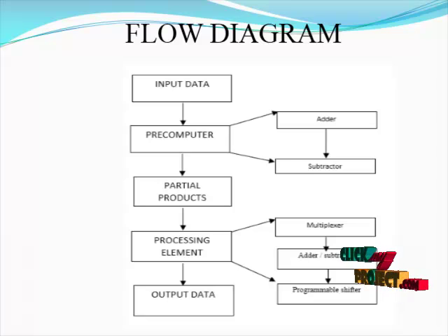The full adder gets two inputs of data, one from the 2x1 multiplexer and the other from the previous processing element. If the processing elements are connected in series, then the previous element output is given as input to the full adder. In case this is denoted as DI, then the corresponding result is given to the mux4.